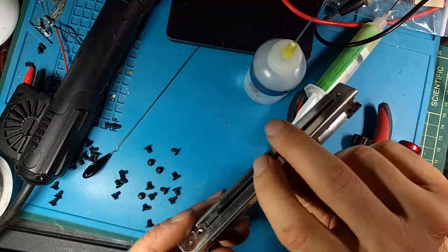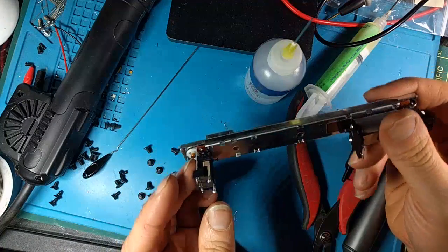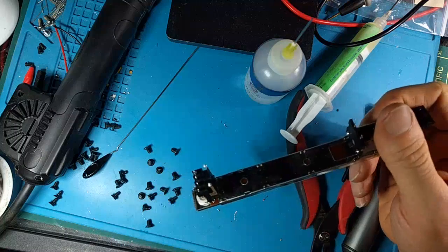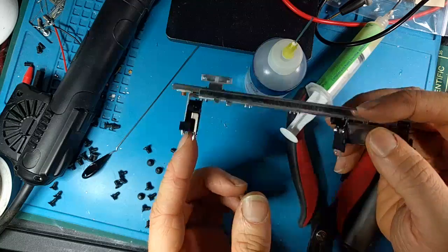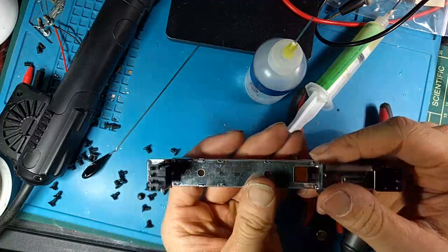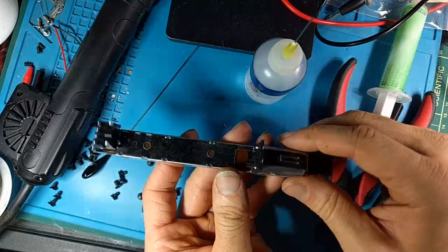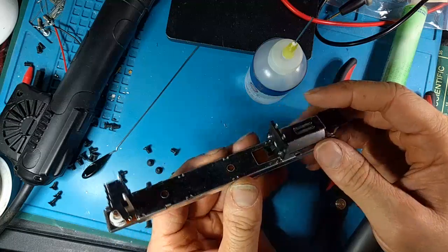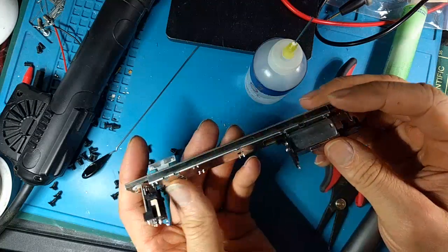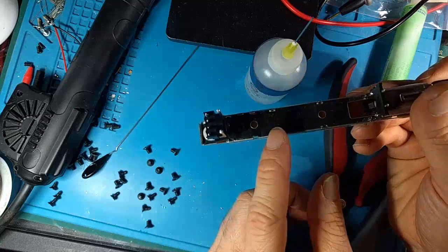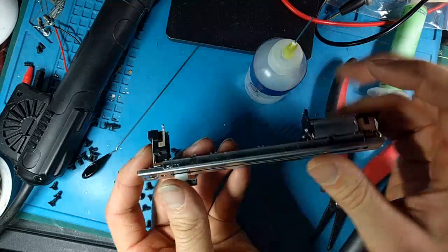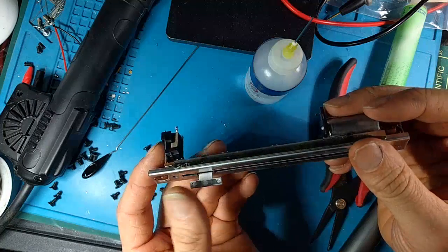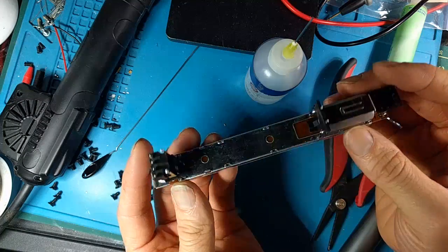And here we are, back with our troublesome knob. I can put my clip leads on this. Actually, I should go ahead and use my desoldering pump to clean up these leads so I can remount it later. But now the next step is going to be very similar to the Control 24 one that I did, which is squeezing out these tabs so that the 2 frames can split, and then you can go inside finally and clean the wiper thoroughly.